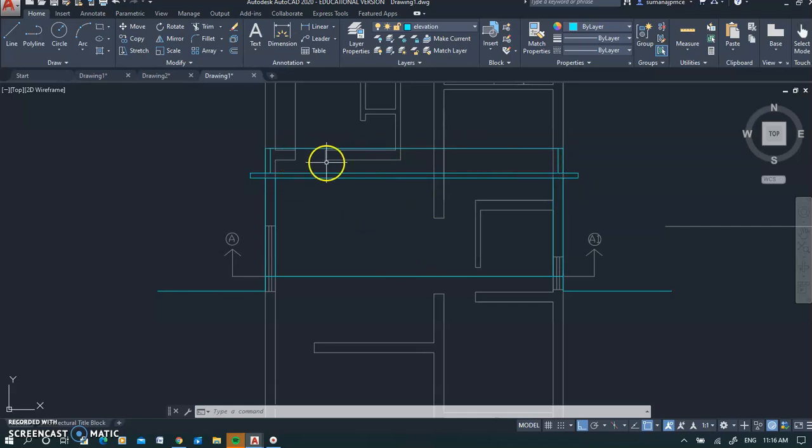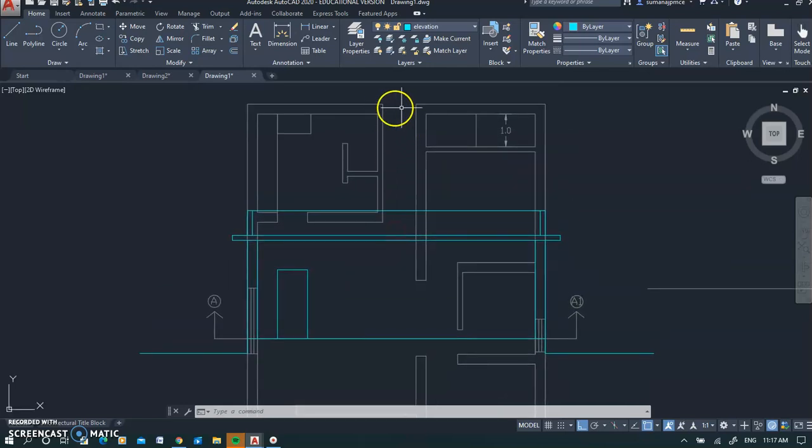Now, this door is seen. So what I do is, I draw a line and I need to draw a door exactly here. See, this is a guide that it is giving me. The height of the door will be 2.1, and the width of the door I don't need to know because it's done in plan. I just need to do that. And I can project that, sorry, I can offset it. But before that I need to join. You see now it is all single elements. So you can join and then offset it. Then you see this door here, okay. So again, line, this door is a little wider, I suppose.